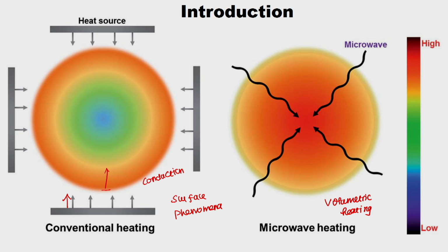If it is convection, as we have already seen, for example, you have a can with a liquid food inside. When the conventional heating mechanism happens, the fluid becomes hot, its density lowers and it rises to the top, and the cold fluid in the top layer comes down and fills this space. This is the convection phenomenon.